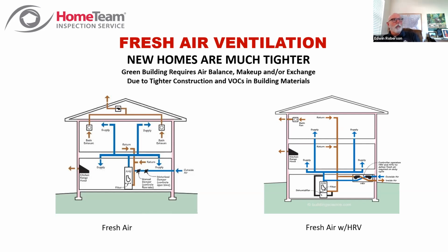And in this case, what we see is typically the system on the left, just a simple, straightforward fresh air system, where you draw that air from outside, but you draw it straight into the return duct of the HVAC system, so that before that air is introduced into the home, it is brought through the system and conditioned when that system is running. And so we see them very frequently.